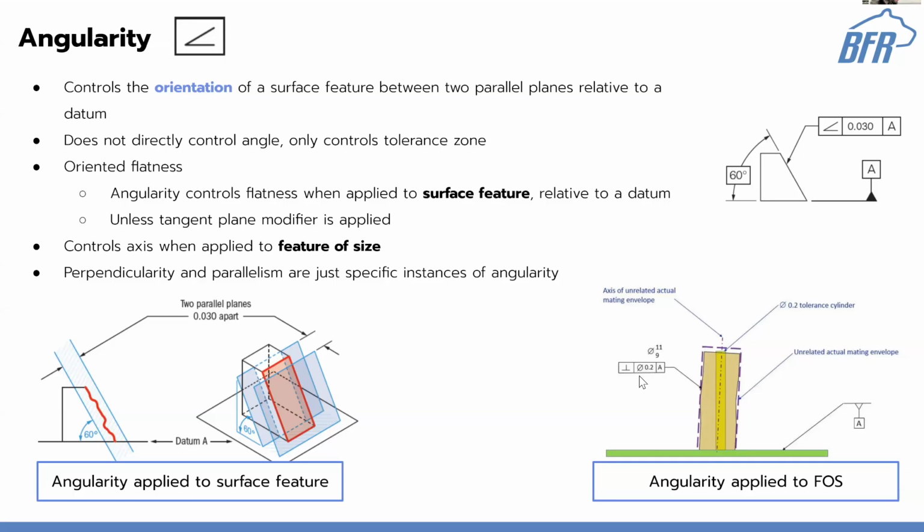And it should be, what's it called? It's a circular tolerance zone because it's got this diameter symbol here. So it makes a cylinder around it. Otherwise, it'd make a box. But it makes a 0.2 inch tolerance cylinder where if the axis of this piece ever goes out of that box, then it now fails perpendicularity. The hole is not straight enough or whatnot, right?